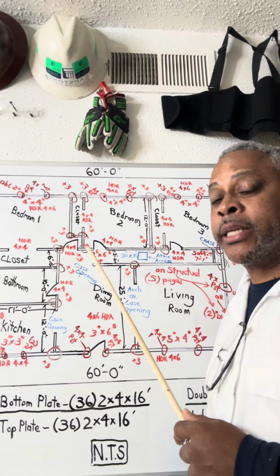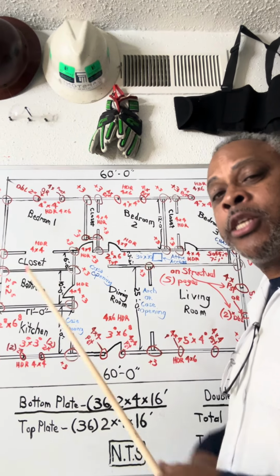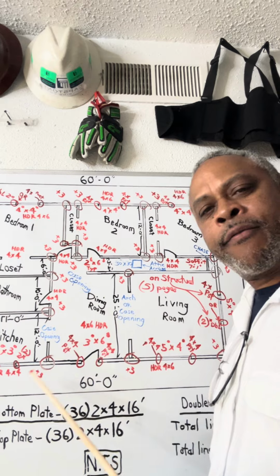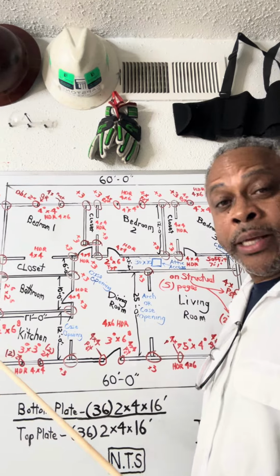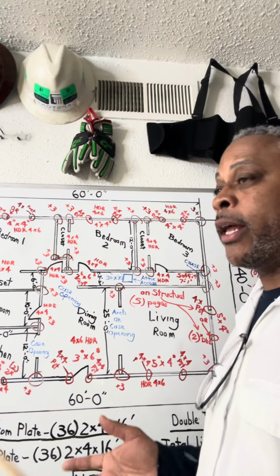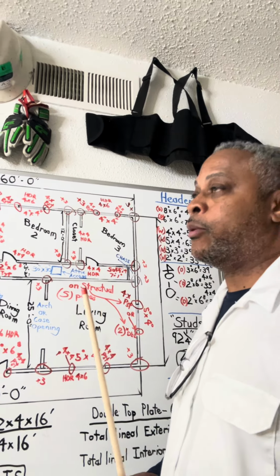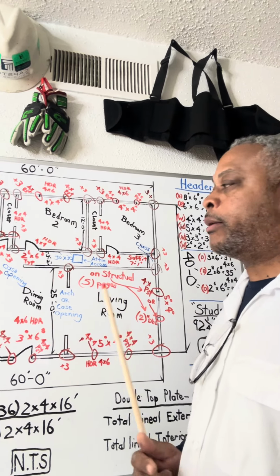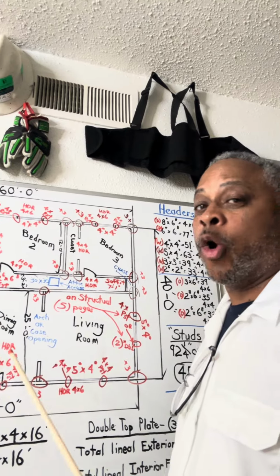Very vital that you understand how to install those, how to really lay that out in the framing, because it can be laid out along with your anchoring, which means there are anchor bolts to lock this thing down to the foundation so that wind and uplift does not pick your place up and move it somewhere else. A Category 5 or Category 4 hurricane or tornado will destroy your home. But they're trying to build better now, so it does not take the whole house away.